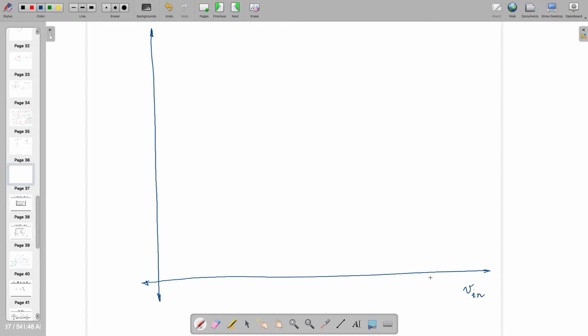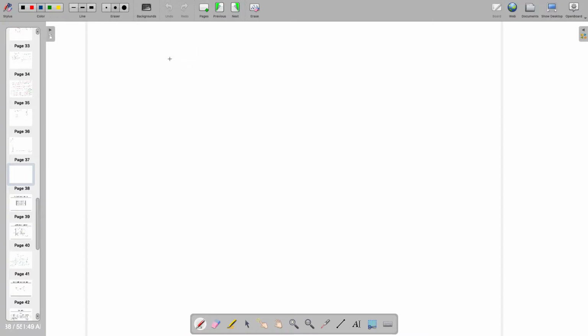So if there is Vn which is on log scale, you might have something like minus 100 dB, starting from minus 100 and going till maybe 0 dB or maybe higher than that. This is on log scale, written in dB. Here this side is V out, it's in decibel. All the signals which are non-linear by nature are going to have fundamental, second, third, and so on. All the harmonics will be there.